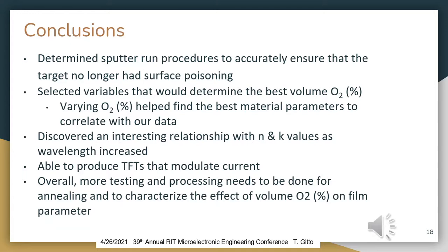So overall, we were able to determine the best procedures to accurately ensure that there's no surface poisoning on the target, selected variables that helped best characterize this film, and this was by comparing a lot of things to the volume oxygen percentage and discovering the relationships between N and K values with the increasing of wavelength, and were able to produce TFTs that modulate current.